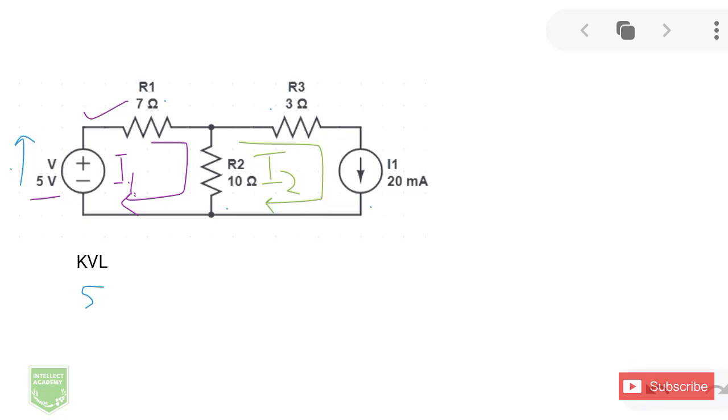And then the 7 ohm resistor. The resistor would have current flowing from this direction to this direction. As we discussed in our previous videos, a resistor basically gives you a voltage drop. Over here, you're going to mark positive and negative for each resistor. This will help you with solving the circuit. I'm going to mark a positive sign where the current is entering the resistor and a negative sign where it's leaving it. It means that there is a voltage drop.